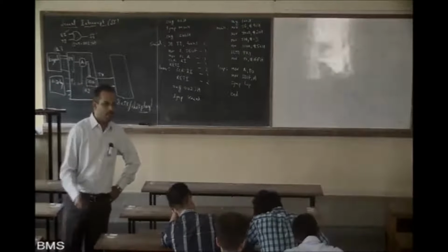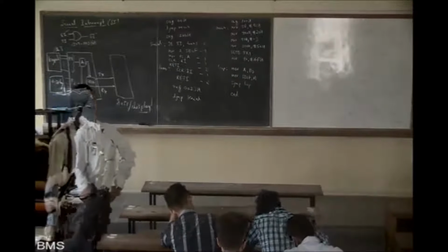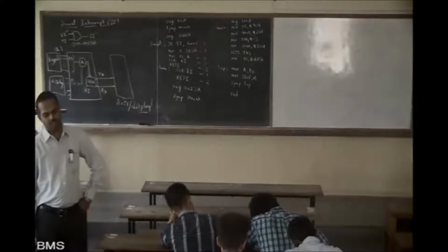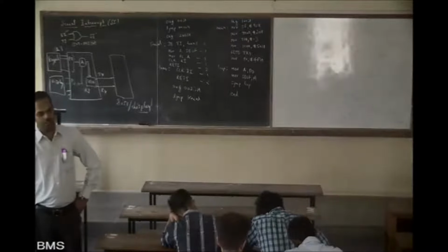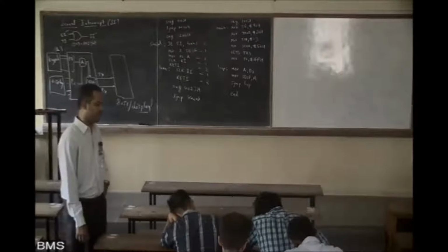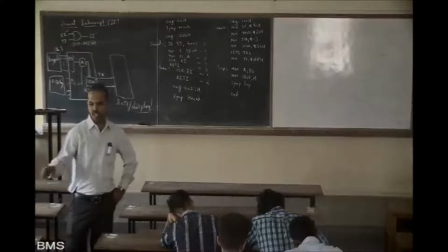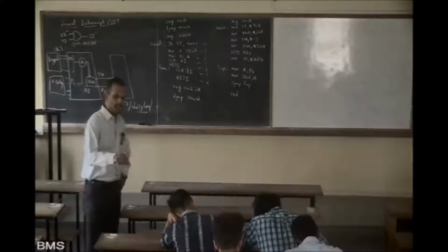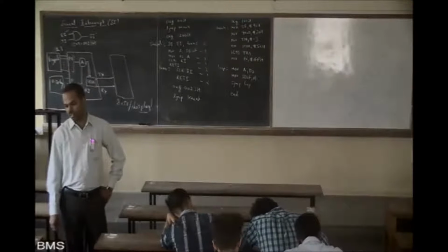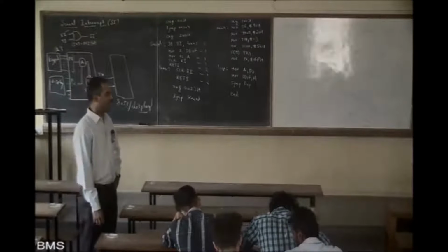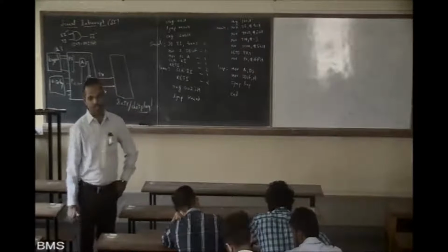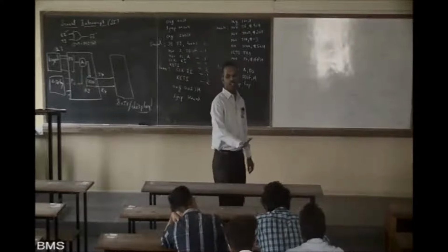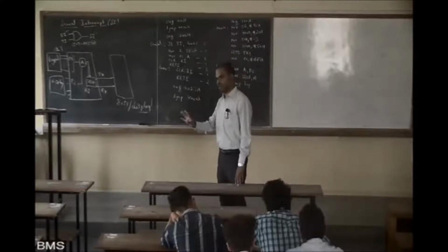Hence, we have to clear TI or RI using the instruction CLR TI/RI in the ISR. In the interrupt service routine, you have to clear this flag, mandatory. If you have understood this, there is no doubt. With this, we have finished unit number 4.